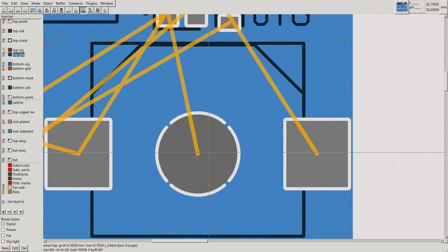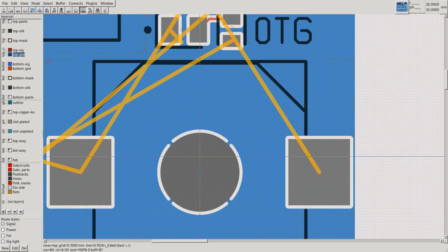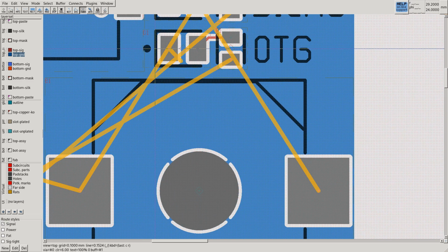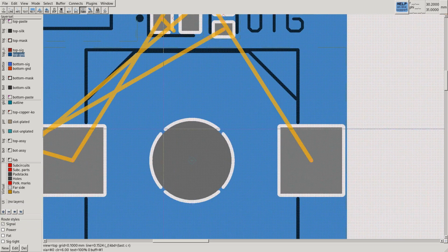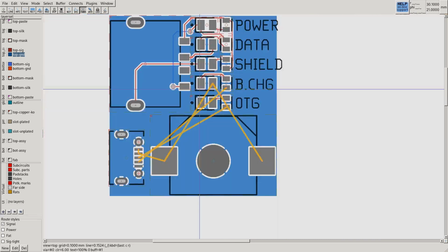So let's click here and you see that it creates thermals around this pad. So now this is connected to this copper plane, and actually if I do CR, you see that this pad, which should also be connected to minus here, they now indicated please connect it to the nearest object, which is ground, which is this copper plane. If you don't like this style of thermal, just press Shift and continue clicking until you find one. And this is how you do ground plane, or you use rectangles and you use shapes.